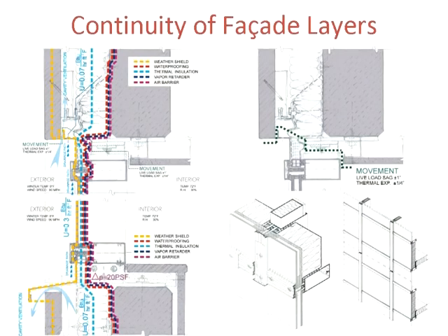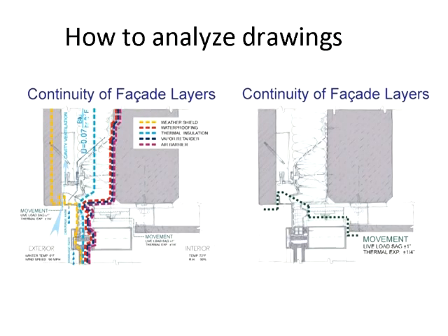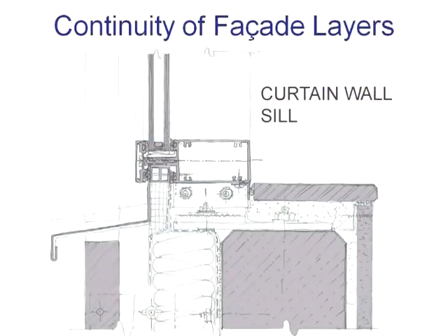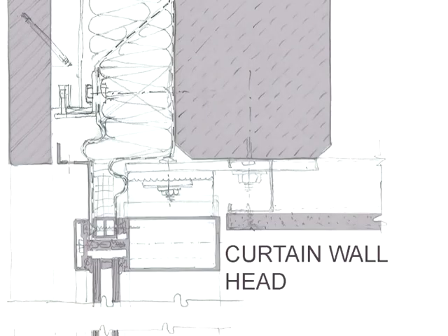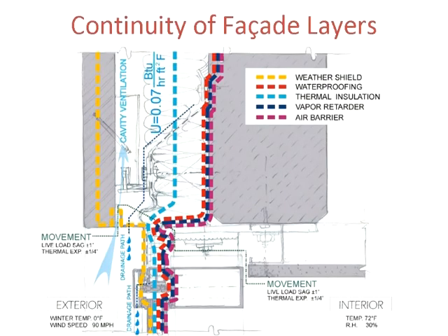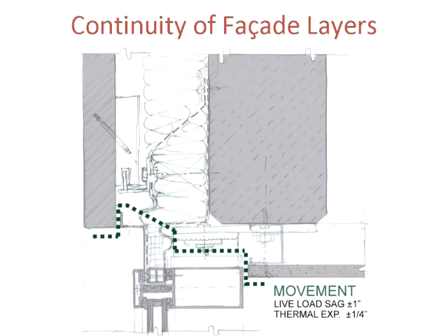Now here are some details that you may remember from the seminar on principles of facade engineering. Here we represent the facade function as a simple line, and we may represent its value, which is particularly useful whenever the value changes. Also it helps to represent the differential conditions, which in turn tell us about the required properties of facade layers. Again, the law of continuity says that you need to trace it continuously, and you should be able to cross movement joints without destroying their functionality.